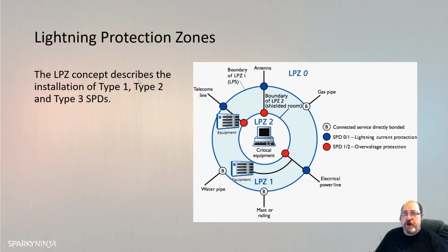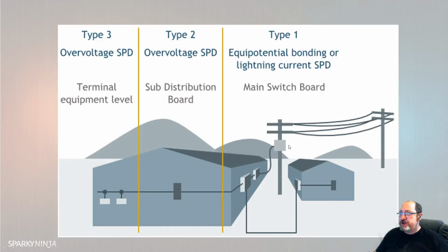sources of this overvoltage. So we mentioned that if you had a lightning strike, it will go down to Earth, but then it could be induced. That voltage that goes down to Earth is looking for an Earth, and if you have lightning strike, let me just use this illustration quickly to show you this. If you have lightning strike an overhead line or a transformer, it's going to send this voltage down, and it's looking for an Earth.